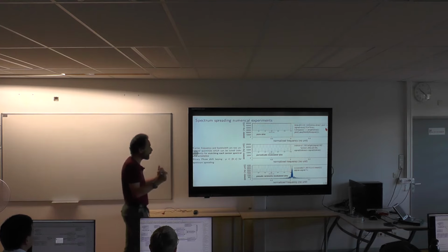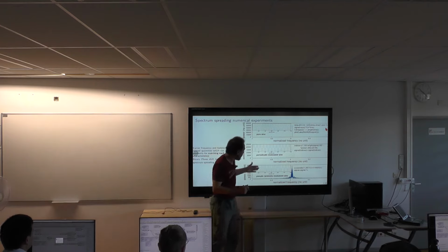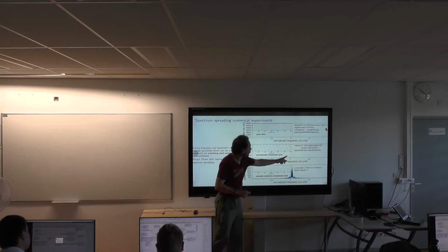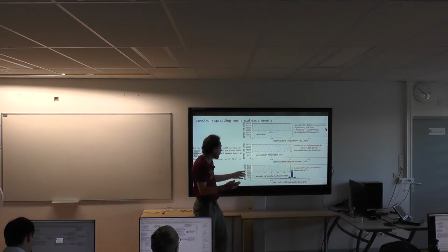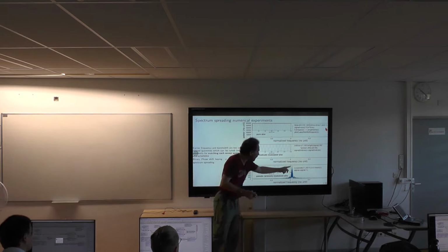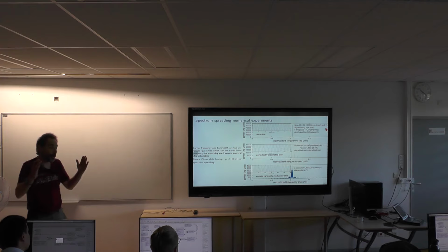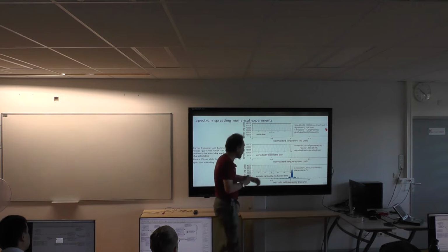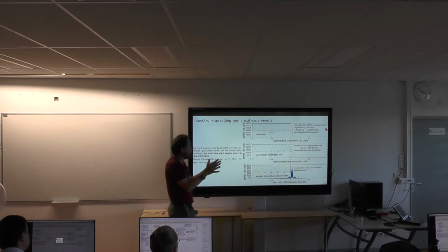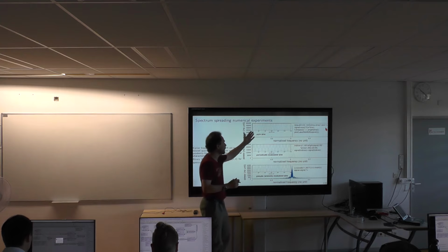So if you look in the spectrum domain, now that we have this random sequence, there is no periodicity in the phase sequence. The fact that we had discrete rays, or spectral components, meant there was a periodicity. Here there is no periodicity, so now the spectrum has become continuous, and the width of the spectrum is the inverse of the time resolution. So the broader the spectrum, the better the time resolution. That's what the story about spectrum spreading is: introducing timing capability in addition to the frequency information that is being broadcast. Okay?